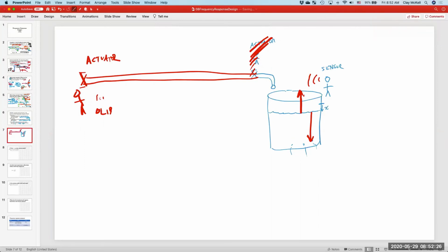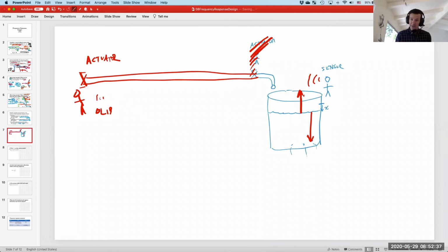How is there a time delay in a circuit with electrical stuff that happens at the speed of light? There won't be any time delays in the analog circuits that we're dealing with. But when you start dealing with much faster systems, and perhaps digital systems, you can start thinking about there will be some propagation delay. Like if all you're doing is maintaining charge on a capacitor, then everything has to happen on the time scale of electron movement in a circuit.